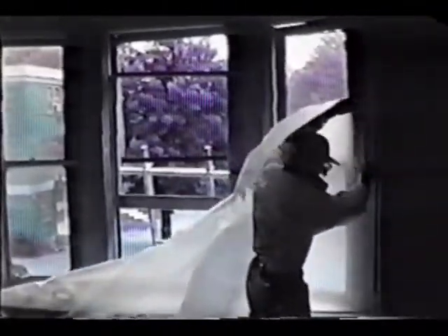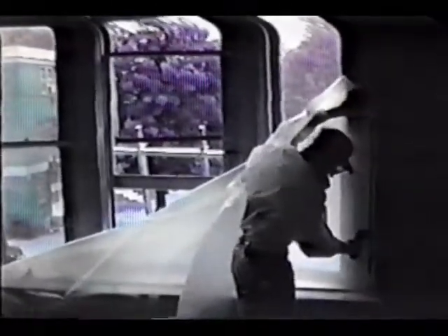To the extent possible, windows should be kept closed during abatements. In cases where windows are missing or are removed as part of the abatement, seal the openings with plastic. If sealing from the inside is not possible, install plastic on the outside.